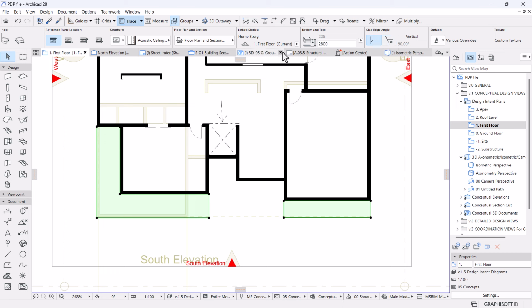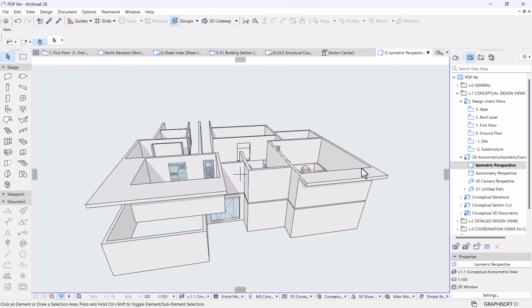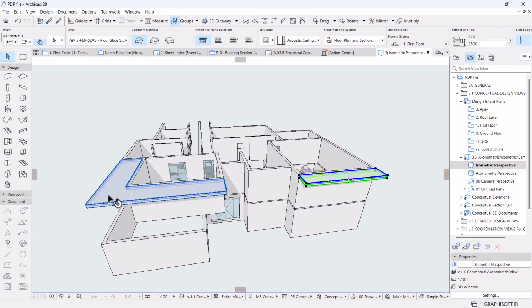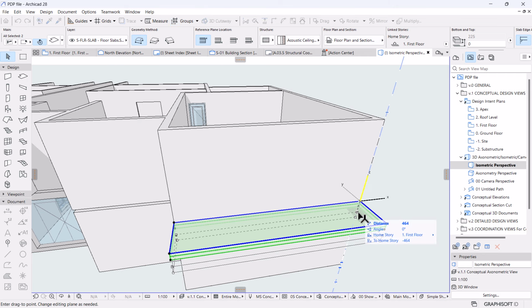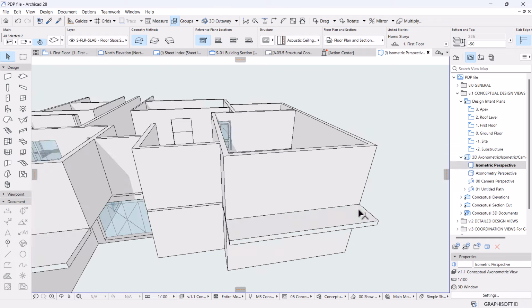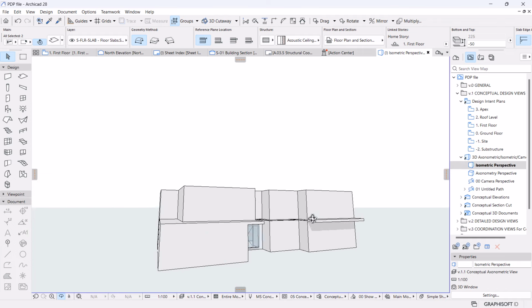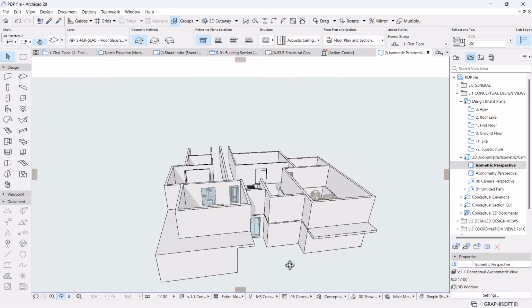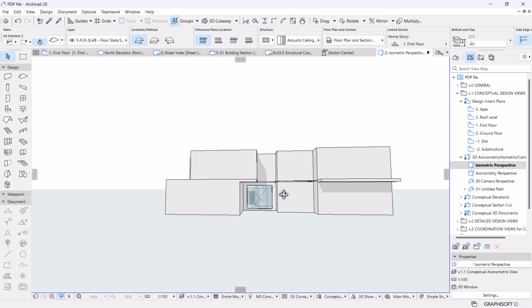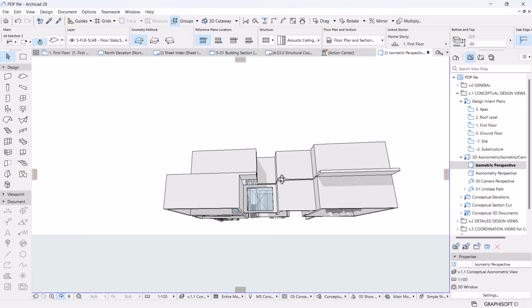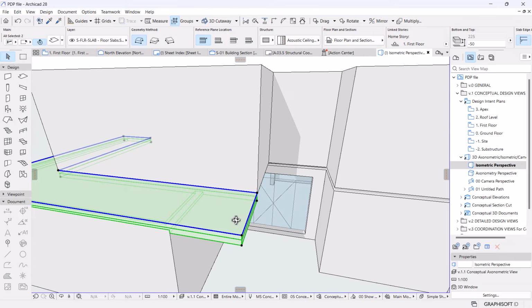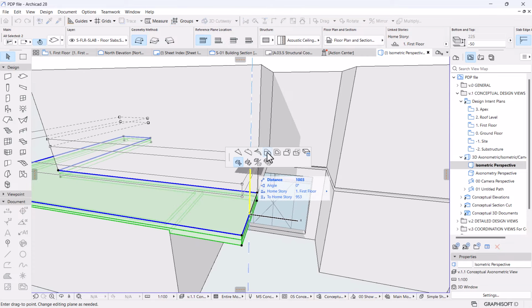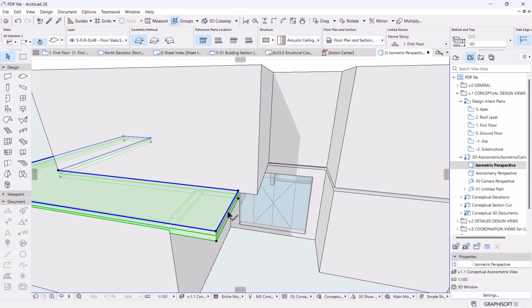So but before we do that, let's check the results in 3D. This should be on the 0, and then I'm going to step it down by -50, just to control water seepage to the internal part of the building. Okay, so that's basically what we have now there. And then I feel this overhang projection is too much. I can reduce it, let's reduce it by 500.